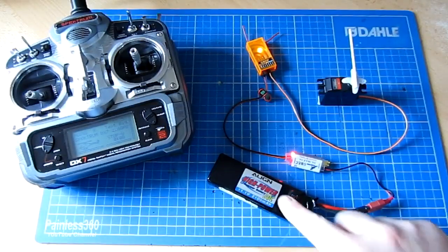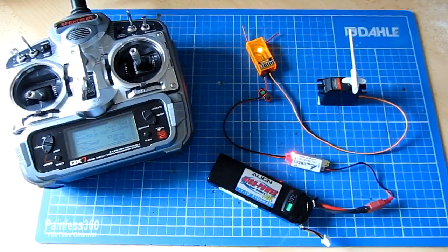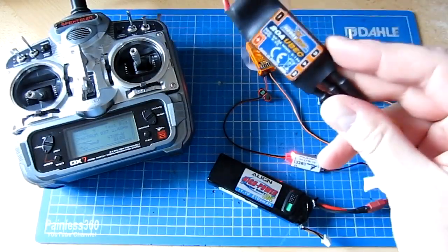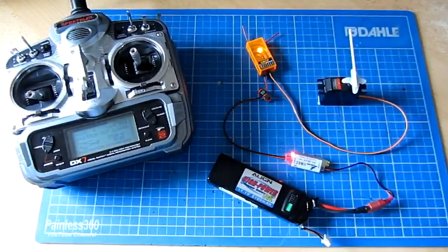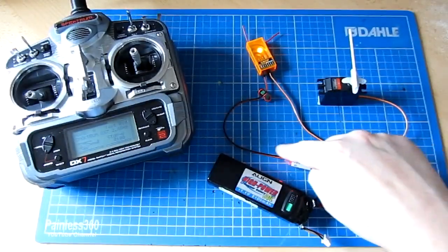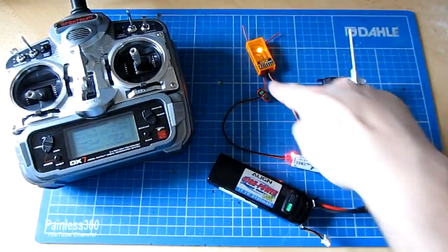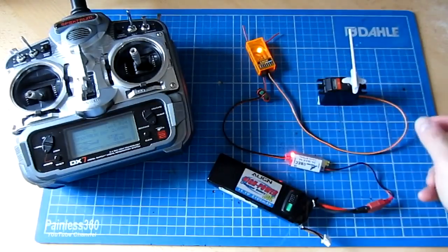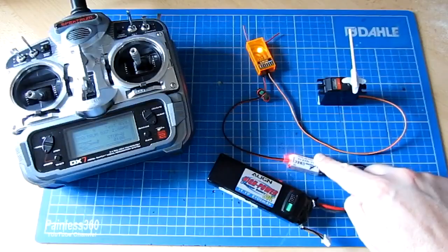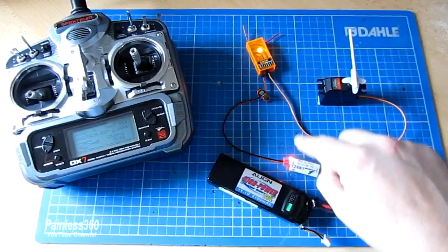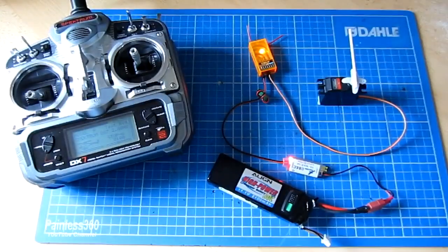So the way it's working is this little battery eliminator circuit, which is actually part of the speed controller that I've taken off the table. There's actually one of these inside here, so that's why we didn't need it before. This thing is providing the 5 volts that's powering the receiver, and also providing the 5 volts that come out of the receiver down this cable and into the servo. So that little box of tricks is giving a nice steady 5 volts that's giving my receiver and the servo all the life they need.